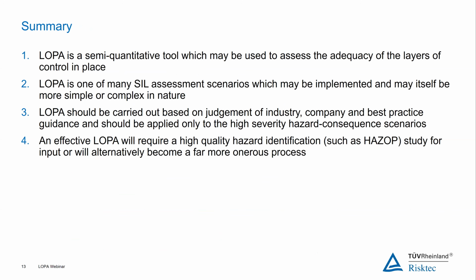So just as an overview here, LOPA is a semi-quantitative tool which may be used to assess the adequacy of the layers of protection or layers of control in place. It's one of many different SIL assessment scenarios which may be implemented. And within LOPA itself, we're going to have more simple or complex LOPAs, as is appropriate.